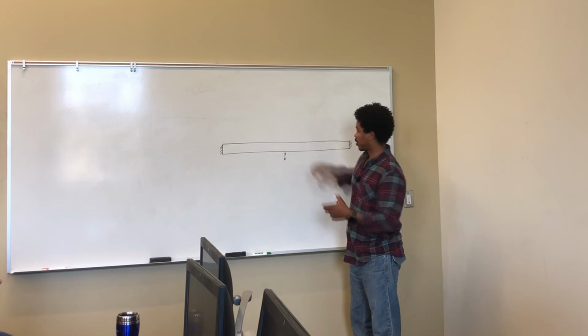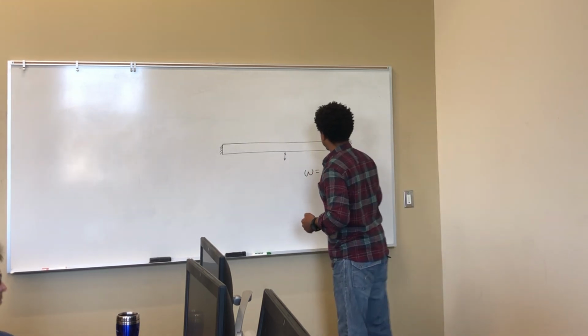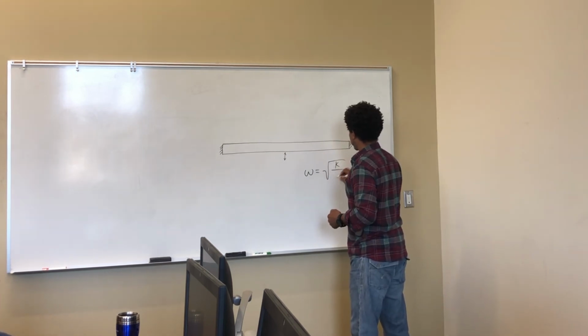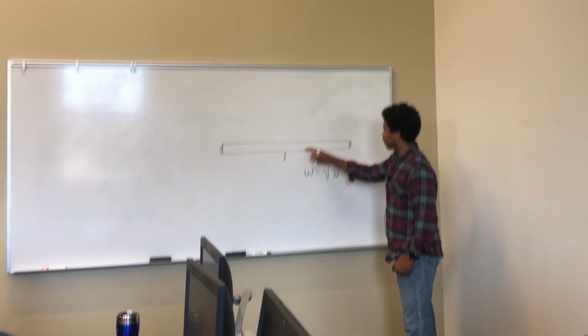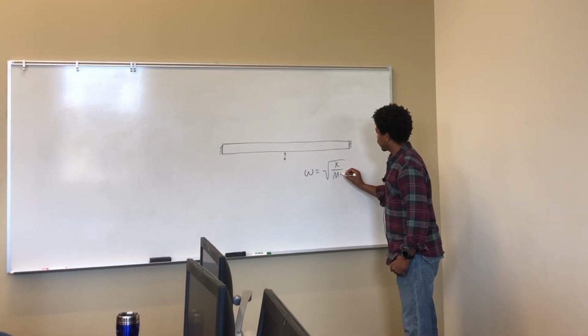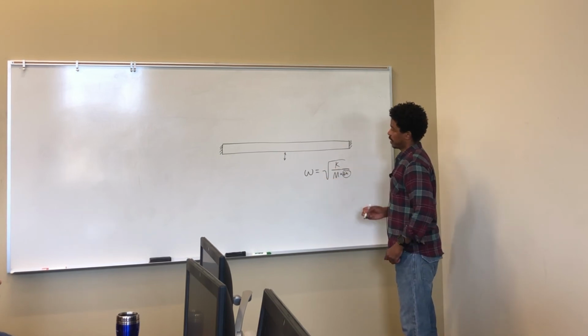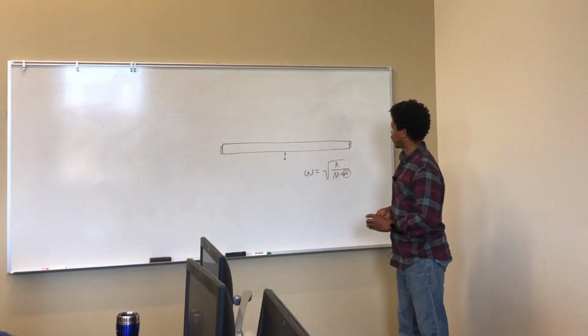mass that is attached. If you remember, the resonant frequency of things for mechanical structures is the stiffness divided by the mass. Well, if you adsorb some molecule in here, you'll have some little added mass onto that. Let's call that delta M. And so if everything is known and you're measuring that, then you can back out of it what this is. And then you can determine what type of molecule is on that nanowire, right?